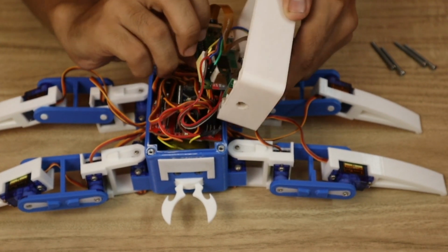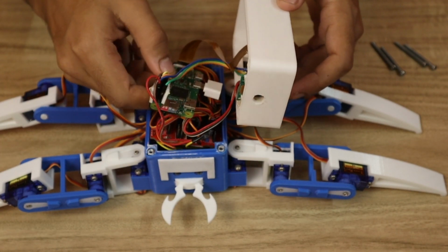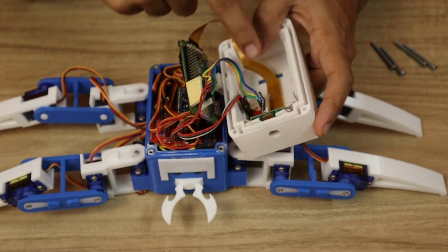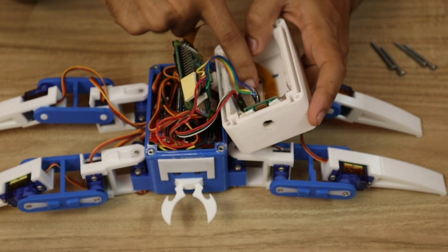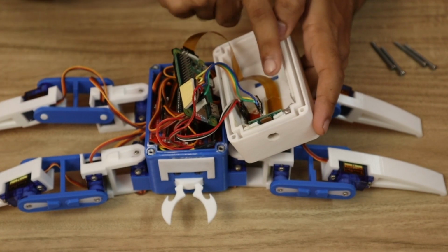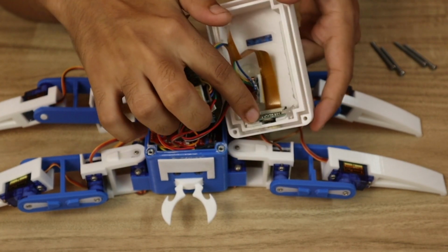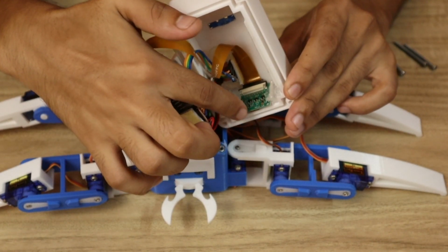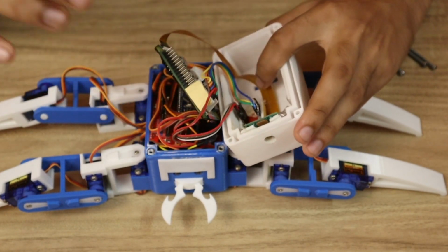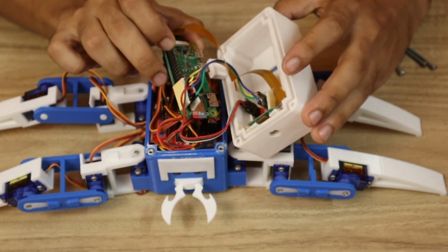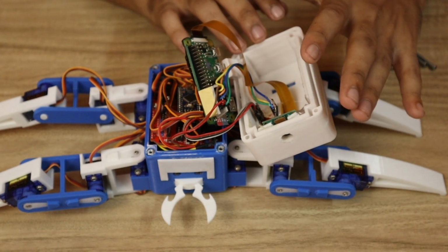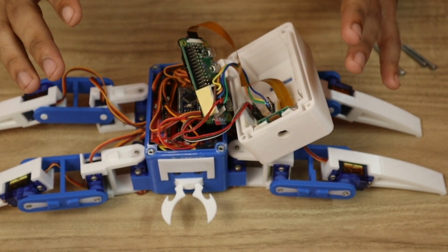So this is the Raspberry Pi Zero I have connected here. Okay, and with the Raspberry Pi Zero I have the OTG, and if you see here I have the logic level shifter. Now I have used some hot glue to put the logic level shifter here, and here I have the camera in the front side. Okay, so from the Raspberry Pi I have taken the camera and fixed it here with the help of hot glue. Here, as you can see, I have attached the camera with some hot glue, and then here I have attached this logic level shifter, and then I can simply put this Raspberry Pi over it in such a way, and then I can close this lid. Okay, so this is how I have managed everything. Though the space is not enough here, to be honest, but still you will manage to put everything.